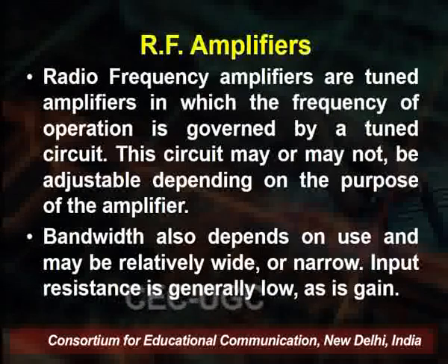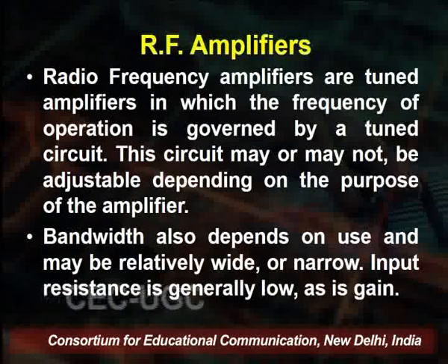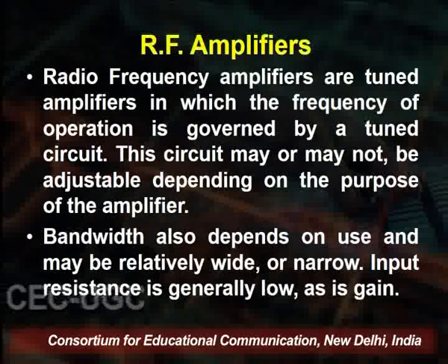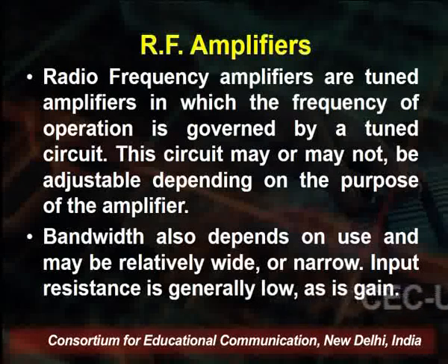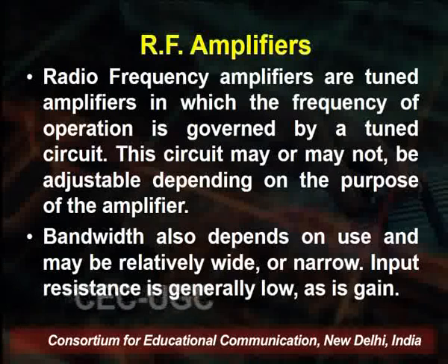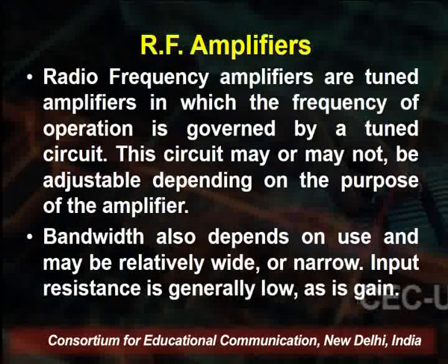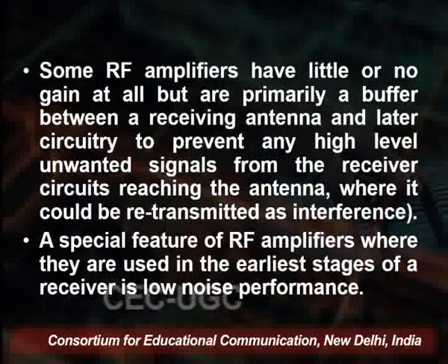Next is the RF amplifier, that is a radio frequency amplifier, which is a tuned amplifier in which the frequency of operation is governed by the tuned circuit. This circuit may or may not be adjustable, depending upon the purpose of the amplifier. As we know, when we change the radio signals we change the tuning, and after changing the tuning we can amplify the signal, and it is governed by the tuned circuit. The bandwidth also depends upon the use and may be relatively wide or narrow. Input resistance is generally low, as is gain.